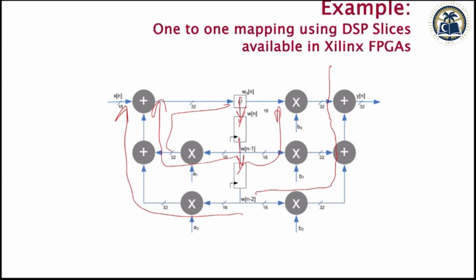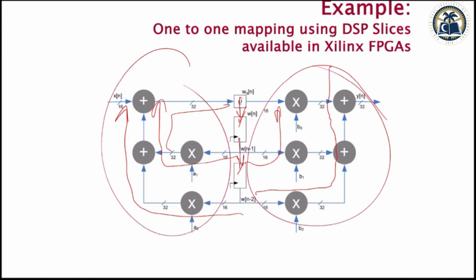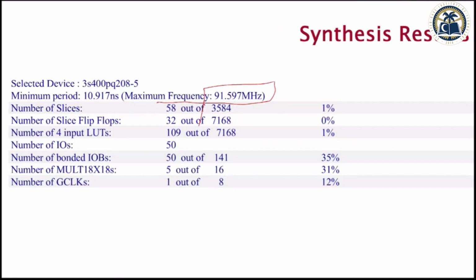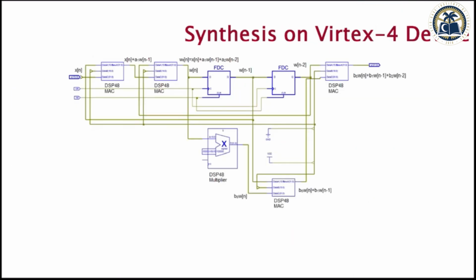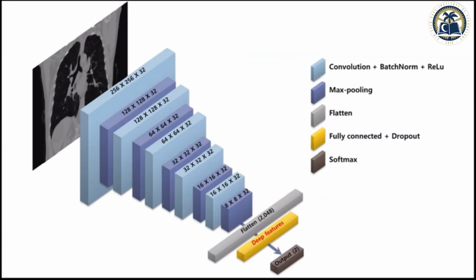It's just a register and a register. It's not breaking anything, so it's not really helping you break the critical path. The critical path is totally separate from the registers adding any value. That's why you need to find out how. Once you map it on Virtex 4, it is now using MACs: 2 MAC, 3 MAC, 4 MAC and a multiplier. It may still improve your clock rate as well.